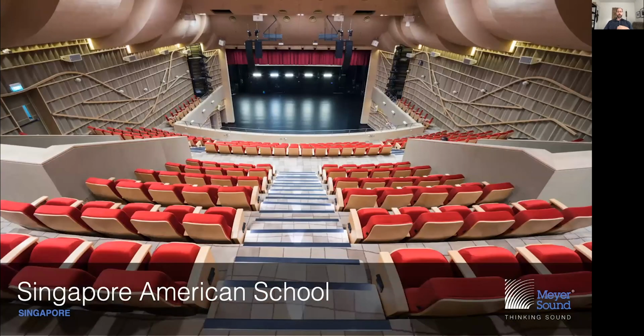As you can tell, the sidewalls are really interesting. These are fiberglass panels in a triangular shape to get a little more absorption. The ceiling was also extremely absorptive, and the seats are very thickly padded, with carpeting everywhere. So the end result is that when they pull down the curtain on stage, this room goes down to 0.5 seconds, which for a room of 900 seats is quite outstanding.